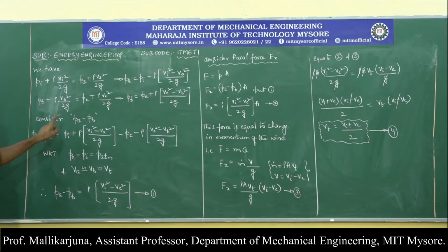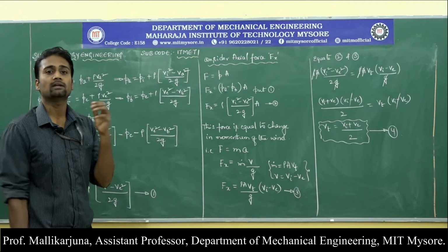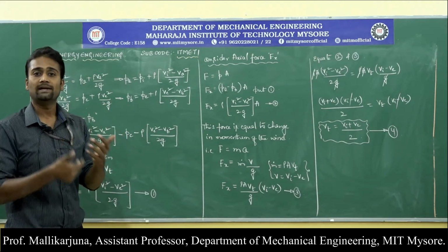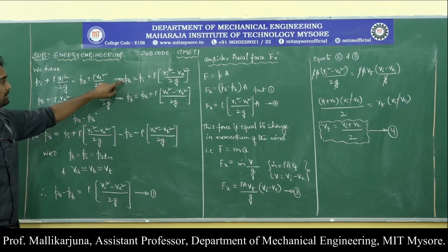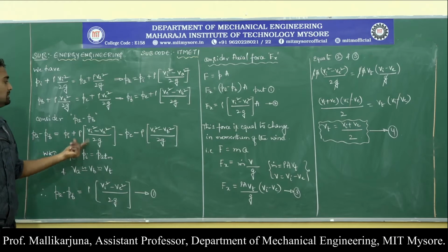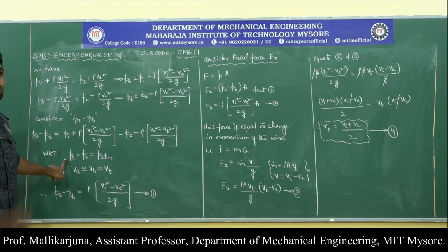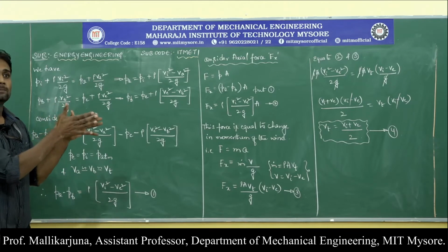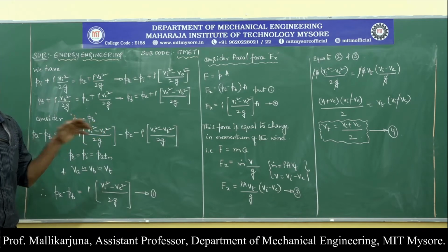Next thing is I have considered Pa minus Pb, because the variation in the pressure on the blades of the turbine is what is going to rotate the blades of the turbine. Because of that, I have considered Pa minus Pb. That means Pb has to be subtracted from Pa. Pa minus Pb will be equal to this minus this section, and here we need to look at a few of the conditions. Very first thing is, if we look at the sketch, the pressure at the inlet section, I mean at the upstream section, and the pressure at the downstream section is almost the same.